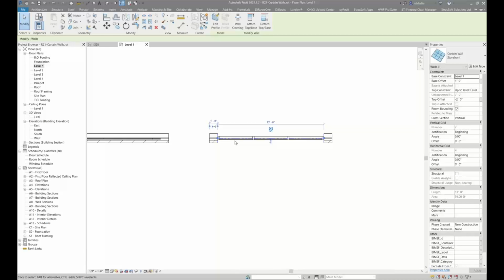So what it's basically doing is it's using the Revit cut command to cut the opening in the wall, but it's not a real opening. So as the size of the curtain wall changes, the opening size will automatically be modified. So technically it's embedding it into the wall.